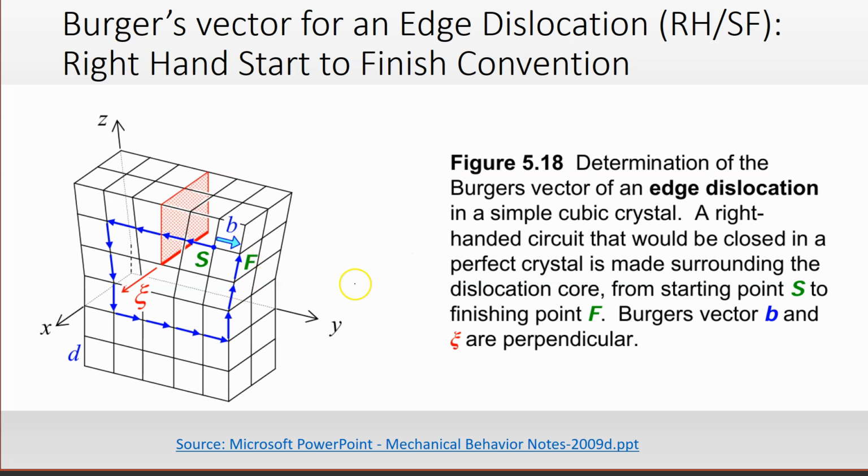So let's look at the two different types of line dislocation. This is an edge dislocation. Okay, this type is an edge dislocation. If we look at this crystal, what's happened to it is as though we had inserted an extra set of planes, an extra plane, in the region hatched red. The bottom edge of that extra plane is highlighted and it's being given this symbol zeta. Oh, I think that's a zeta. So let's call it a zeta for now.